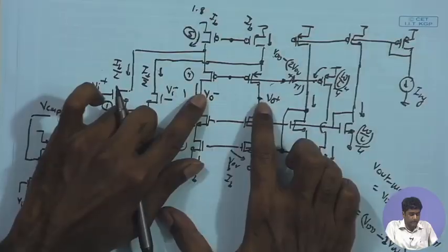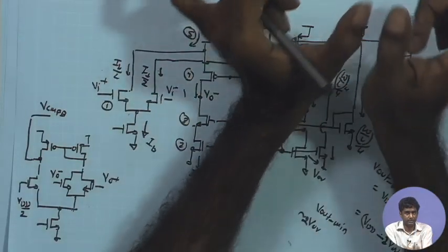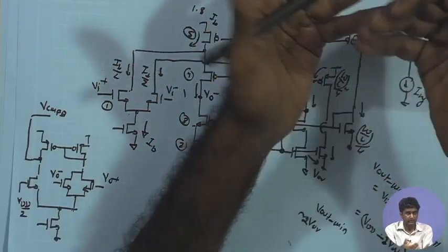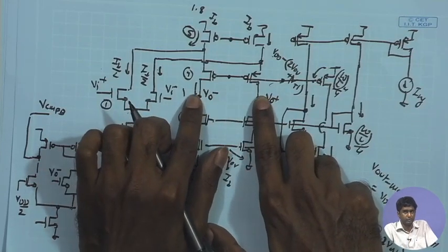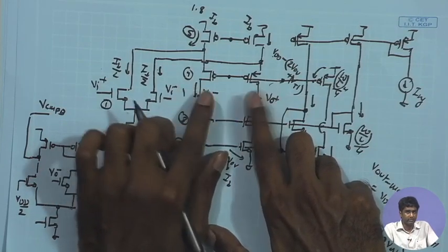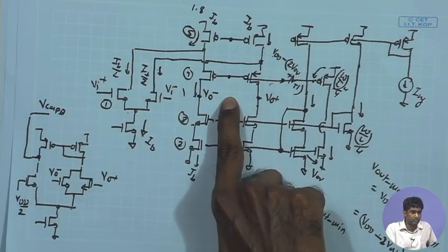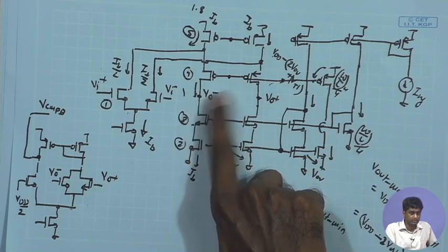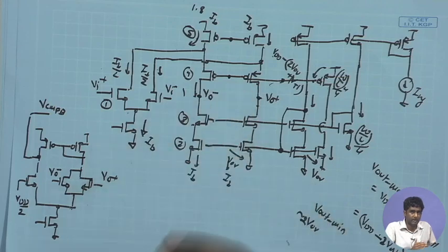Once again, yeah. So, there the high impedance resistor you are realizing using a transistor. So, that is a very high value. So, as compared to if you use such high resistors to extract the common mode, they are very imprecise. So, for common mode we want that these two resistors should be matched, whatever resistors you are applying over here. So, if we use such active devices operating in the subthreshold region and expect that they will be able to extract the common mode voltage, that is not a very practical way, because each of these active or MOSFET based resistors will have a lot of process variation, and will not be very well matched.